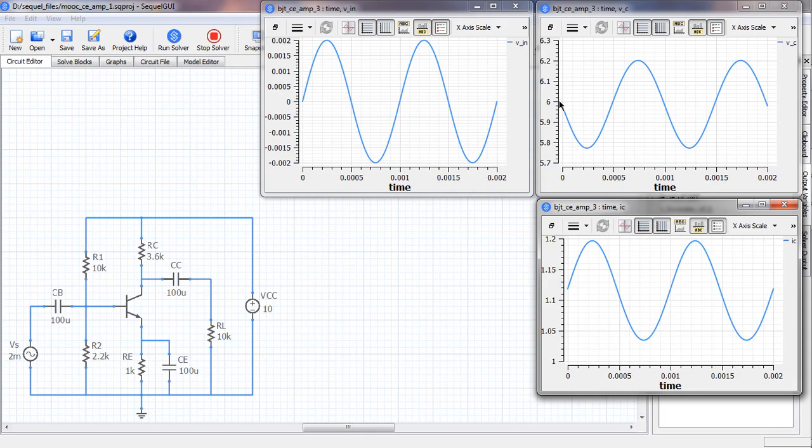Its base value or the DC value is indeed 6 volts, very close. And the peak to peak variation here, let's see how much that is. This one division is 0.1 volt, so we have 0.1, 0.1, 0.1, 0.1, and maybe 0.02 or something like that. So it's 0.42 or 0.43, and we expect 0.45. So it's reasonably close.